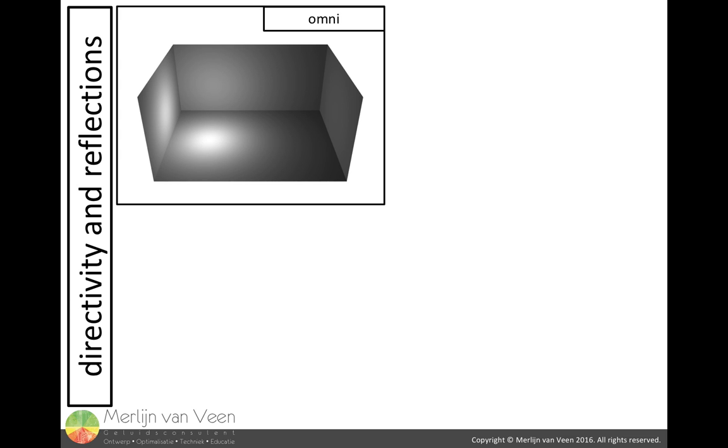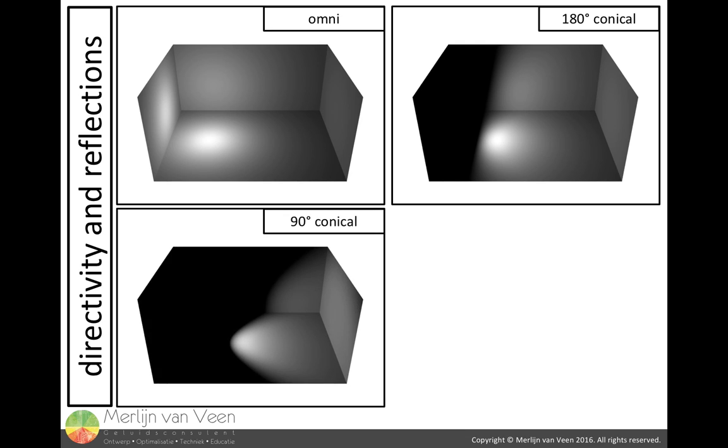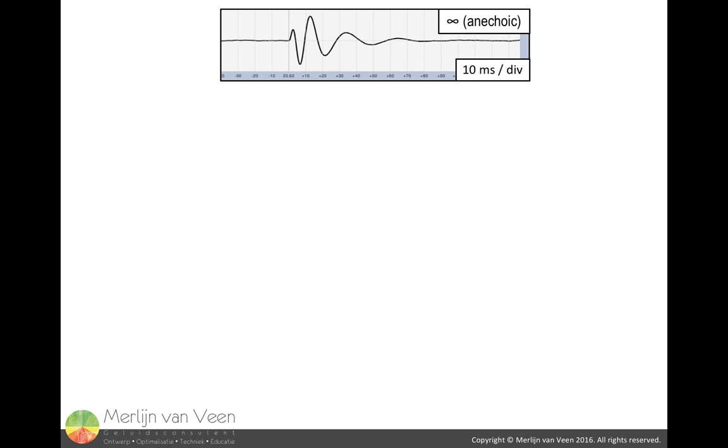Indoors, however, far more challenging is the destructive behavior of low-frequency reflections. Due to their near omnidirectivity, subwoofers, in contrast to directional speakers, aren't capable of avoiding the room. They excite and illuminate the venue with sound maximally, introducing lots of reflections that wreak havoc on both transfer function and impulse response. This would be our virtual subwoofer in an anechoic environment with maximum direct to reverberant ratio.